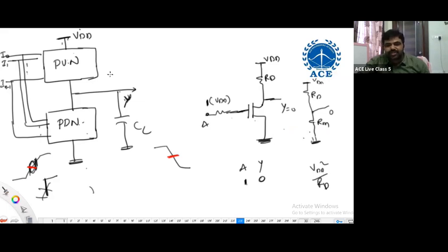When inputs are switching, there is a possibility for switching outputs. So switching power is the energy stored in the capacitor that will be dissipated when the output is switching from logic 1 to logic 0. Whenever it becomes logic 1, it draws current from the supply, that is dissipated through the pull-down network.